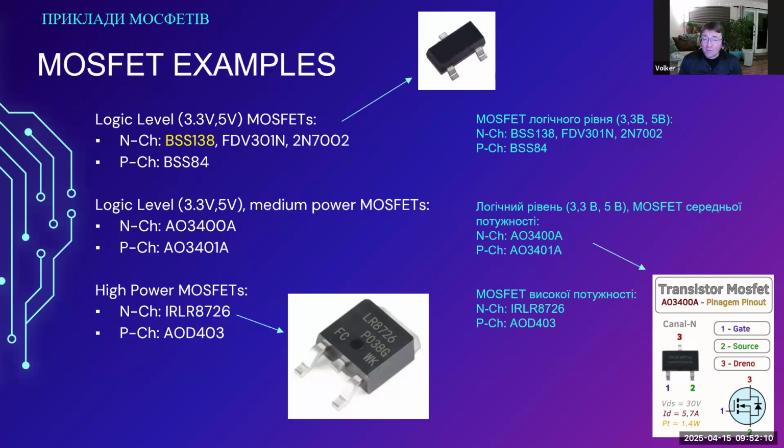which is kind of, again, on the iffy side, because the silicon, the actual MOSFET die might be rated for that, but it is an SOT23 package MOSFET. It is the same package as the BSS 138. So you have to be really, really careful not to overheat that package because it has no heat sinking capability. I think it is rated for about 300 milliwatts of power dissipation. So the MOSFET itself might be rated for 5.7 amps, but really don't push it that far.